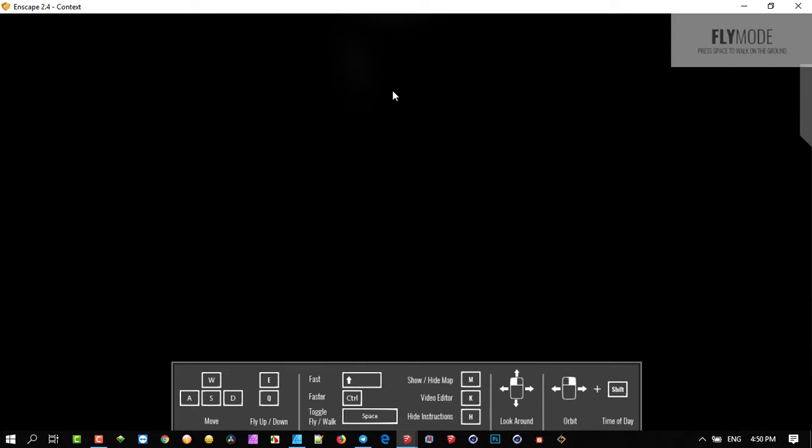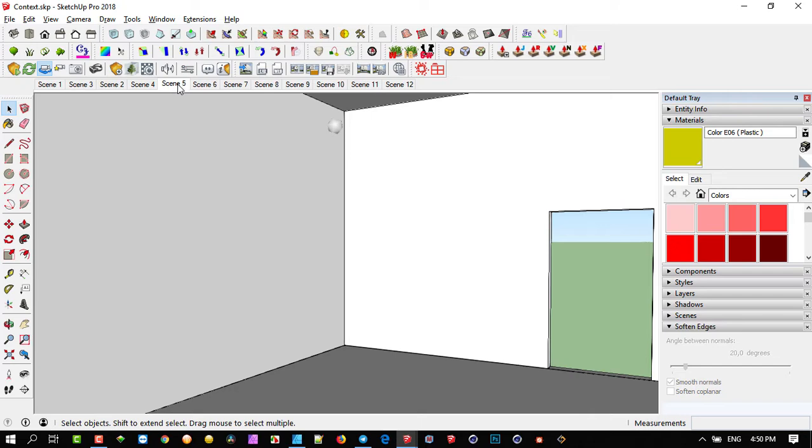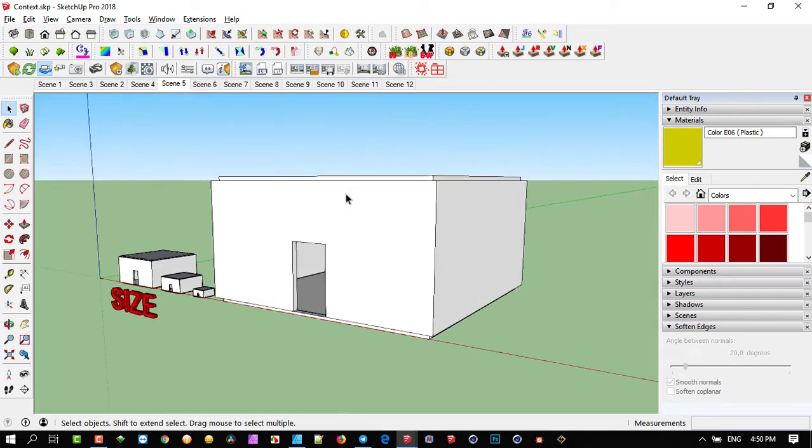Now this doesn't work. Then go back to your size, go back to your scale, and maybe the model that you've created is 20 times the actual size it should be. So then get it down to be more realistic, and the light would work better in that. Same thing with materials and so forth. So when I do the video on materials and lighting, we'll probably cover a few of these areas again. So just remember, the key point with realistic renders is the size of the model you're working with. Because if the size is out, then the materials and the lighting are not going to gel very well with it.